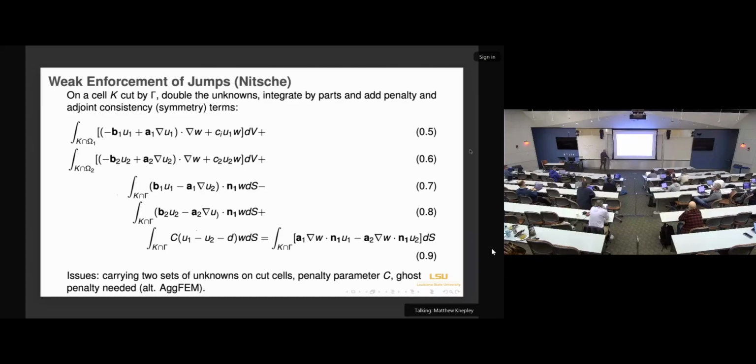Okay, and that's kind of associated with this Nitsche approach anyway: you're not strongly enforcing the Dirichlet condition, and so you basically have an extra source of variability there. That can be a problem if you're trying to, say, do air-water flow and you're tracking the phase interface as it's moving and breaking and all that. The cut cells are going to have to carry an extra set of degrees of freedom on each one of those cut triangles, which is going to be moving around in space. So a little bit of a pain from a computational perspective.